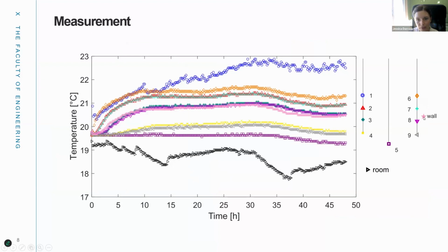And what we can also see is that our tank isn't actually as insulating as we hoped for, because the wall temperature here, which is close to this temperature probe in the water, is almost the same. So hardly any insulation there on the walls. Also, interestingly, we can see that this temperature sensor, which sits just below the heat source, almost shows no impact from the heat source, which is interesting because it means the thermocline is really close to our heater.